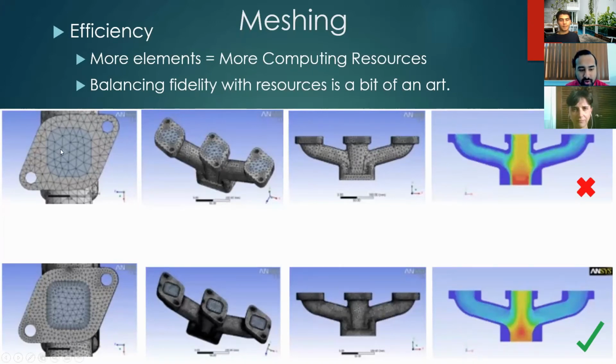So if you take a look at this top geometry here, it's a very coarse geometry. You have this fluid domain in blue and this structural in gray. And if you take a look at the result of the fluid, it looks like you have this inlet coming from the bottom here and then separating to these three components here. But it looks like the flow is not in the center, it's actually sort of in this block region here, and then it deviates. But that was likely just an artifact effect because your mesh is not fine enough.